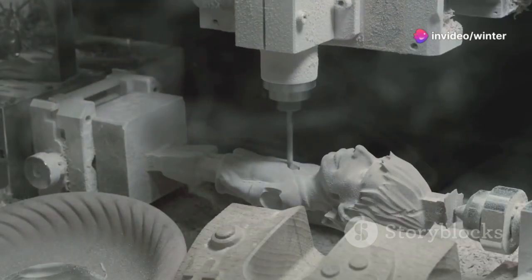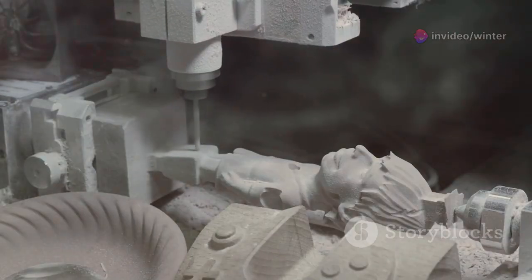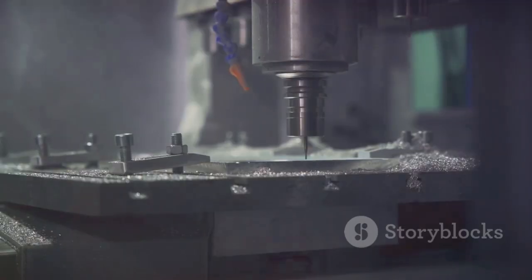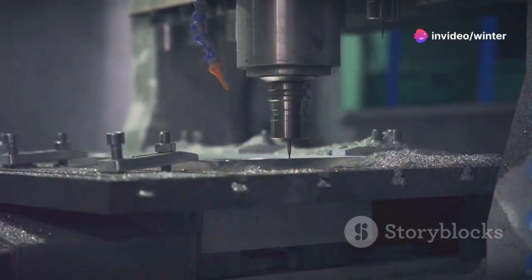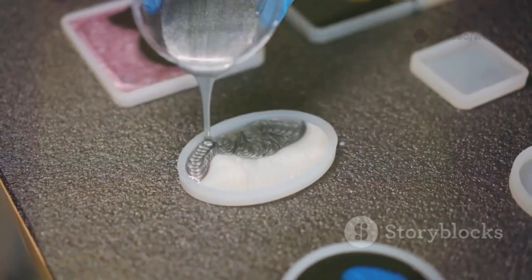Hardened tool steel molds are expensive and slow to make, but last for millions of cycles. They're essential for high-volume production and tough plastics. Pre-hardened steels like P20 offer a middle ground, affordable, durable, and good for medium runs. Don't over-specify. Choose the material that fits your volume and budget.